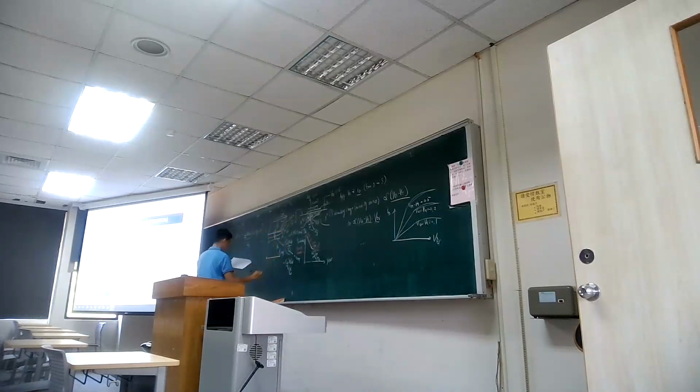So if you want to see the corresponding voltage, here is the 0 volt, here is the VS. You apply the VDS along the drain to both sides. And here at VDS, you can take any point in between as the corresponding condition. Here we label 0 to X, and here is the voltage at point X.